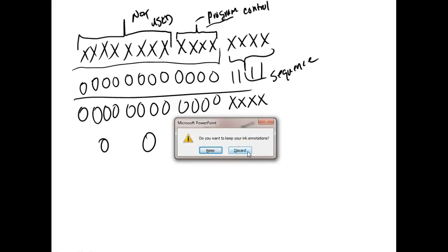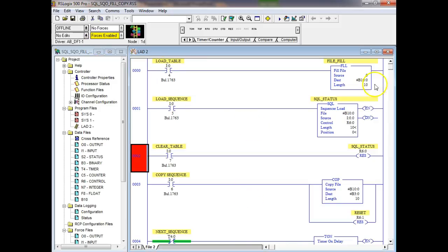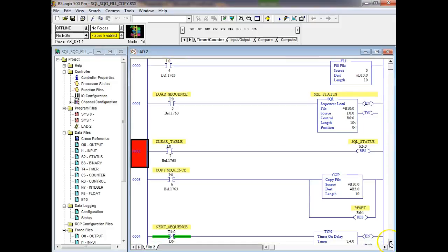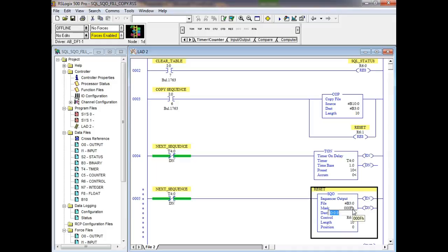And like this is the 1100 PLC. So we're offline. So we can come up here and go to our mask, which is down here. So let's put in a number, and we'll enter. And of course, it took that as hex. So it looks like no matter what you enter, what I did was I entered a decimal number. I entered 255, which I know is what? FF, yeah. 255 is FF. So even if I enter decimal, it's going to show hex.